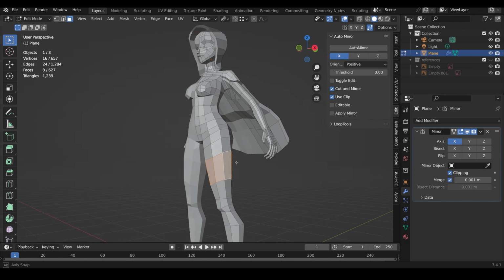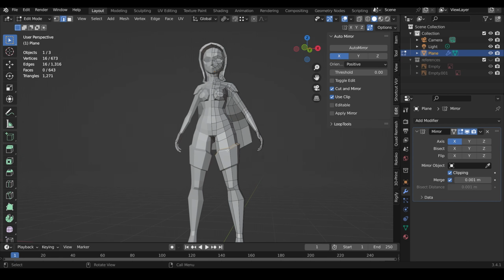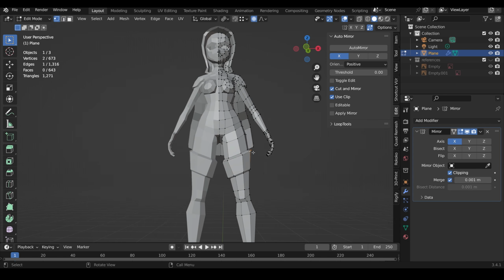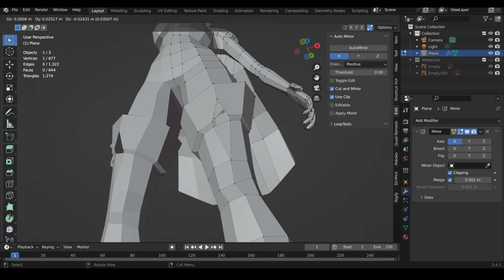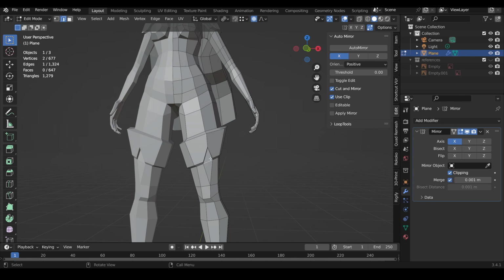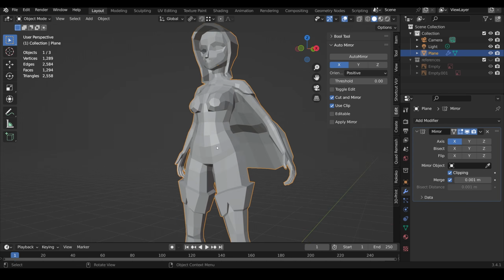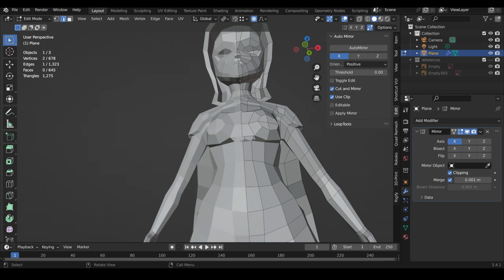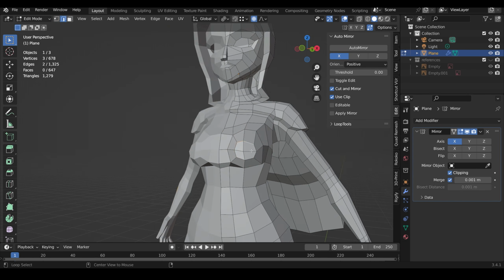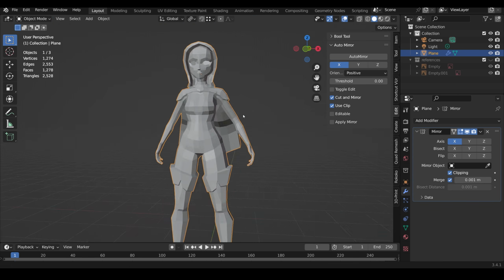The other parts of the clothing are fairly straightforward and kind of obvious in a sense. You just take a face loop and extrude it out. I usually give it a little bit of a slope so it's not coming out straight away from the mesh. It's got a bit of a bevel on it. And of course, make sure you look at lots of reference images and get a style that you think works with your character. You don't always have to extrude the mesh out. Sometimes it's a case of just texturing it differently. And sometimes for something like the top here, it's a case of deleting the middle section and filling it in.